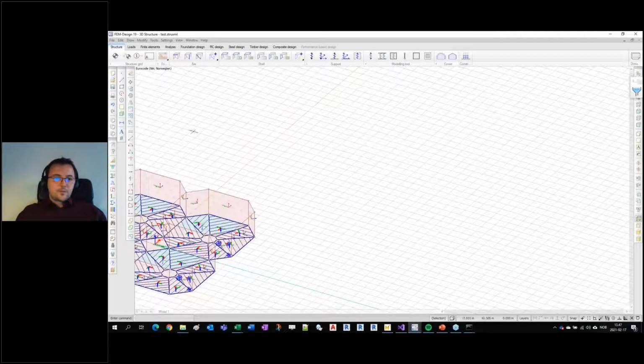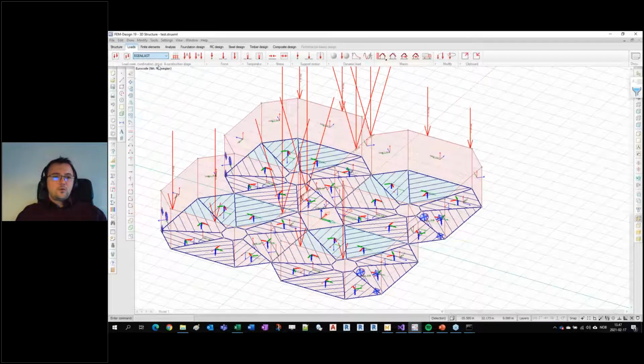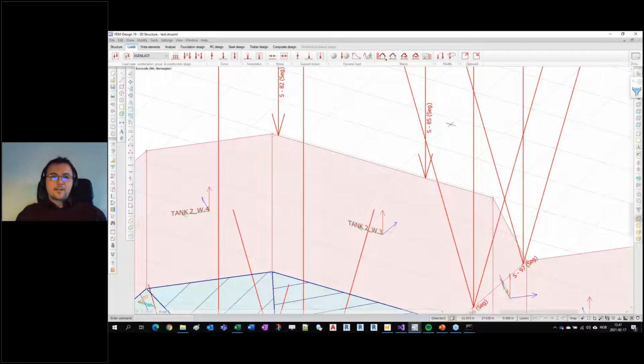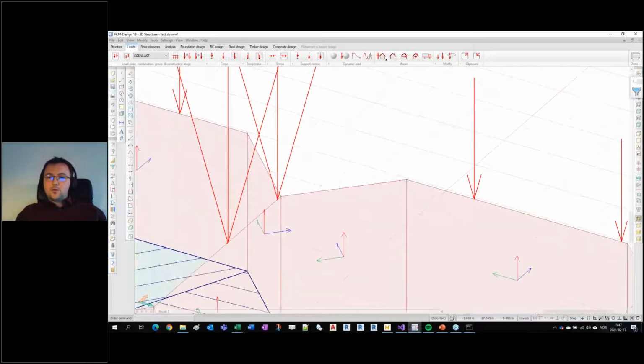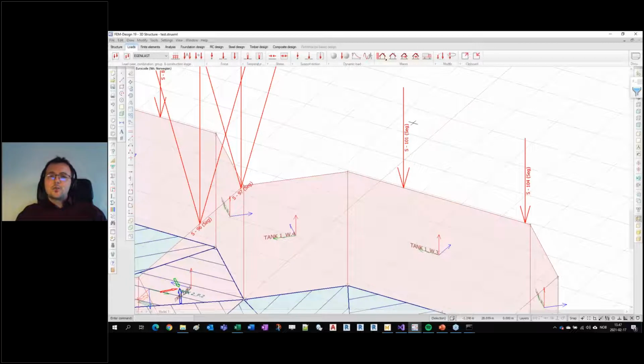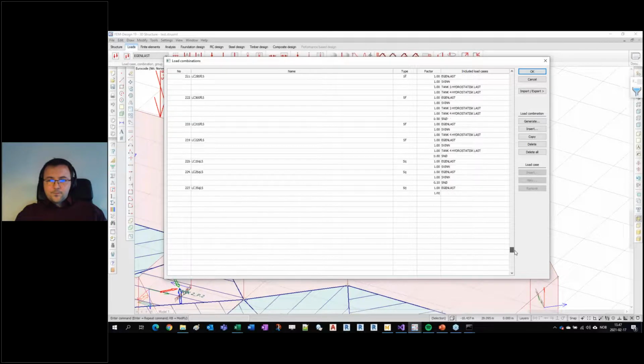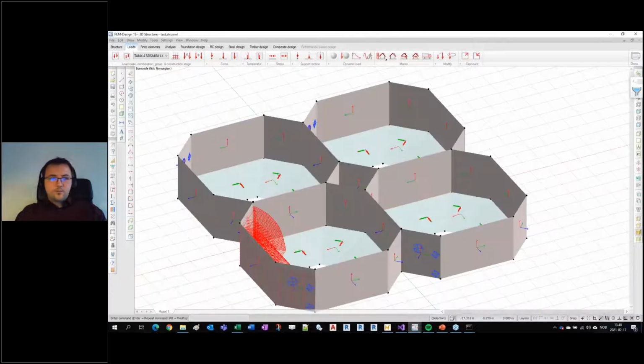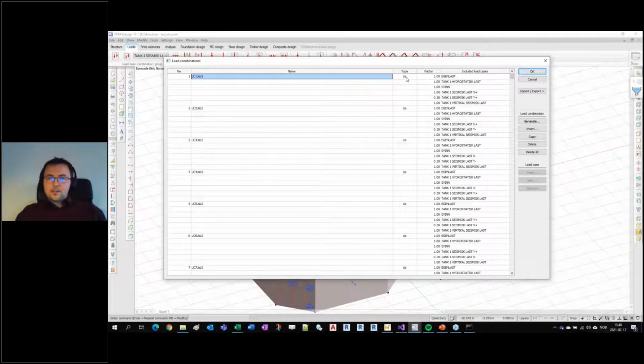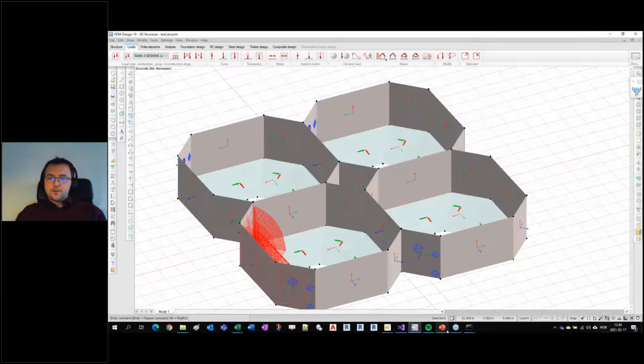Model. So let's see here. There are loads for different load cases with comments of the axis names. So it's easy to follow and check from Excel and the information that we get from the steel designer whether the values are modeled correctly in FEM-Design. And you can see that load combinations are of type ultimate and serviceability type, while on the other model, which was ultimate seismic limit state, they are of type seismic limit state. And of course the safety factors correspond to the combination type and also to the load category according to Eurocode 1990.